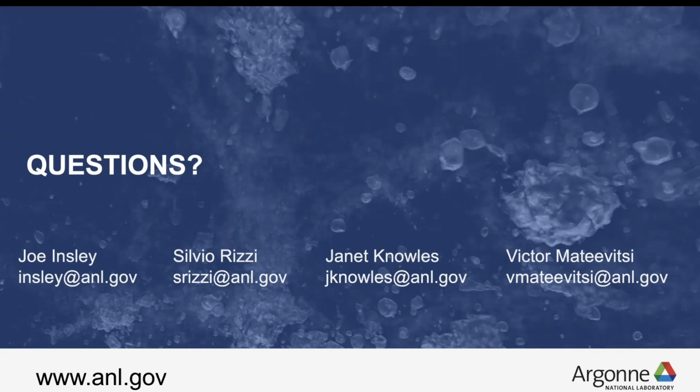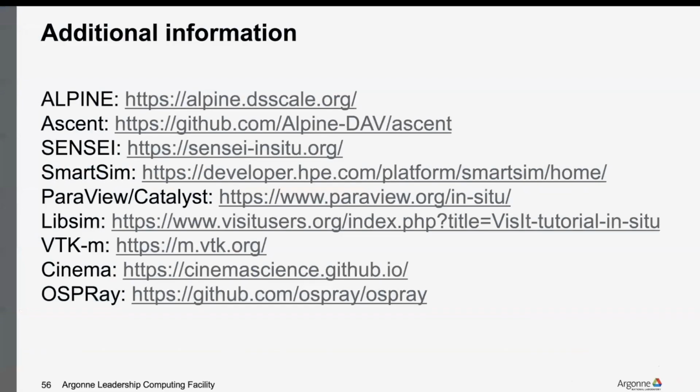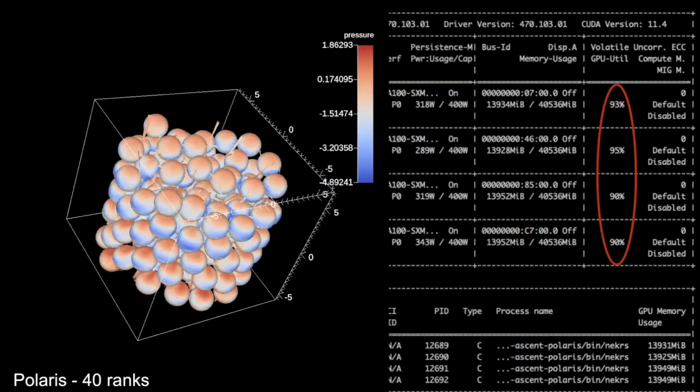But you mentioned the need to convert mesh elements. I think we talked about this the other day too: there's the tetrahedralize filter in VTK, and so that could potentially be put in the loop. You'll have to fill me in if I'm wrong, but it may or may not be implemented in VTK-m, the tetrahedralizer. That will take different mesh elements and essentially turn them all into tets.